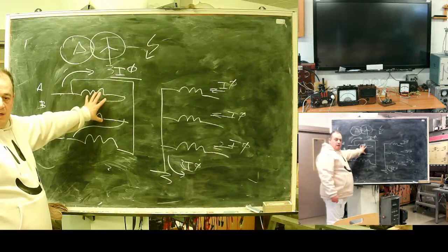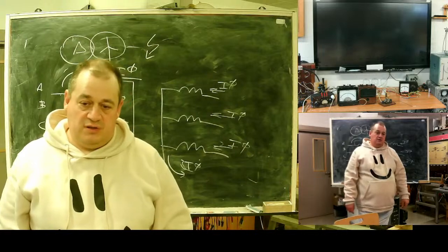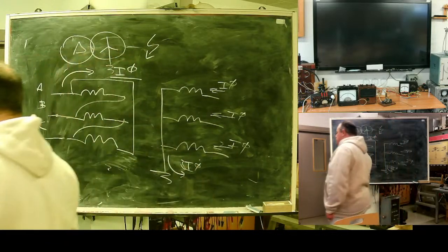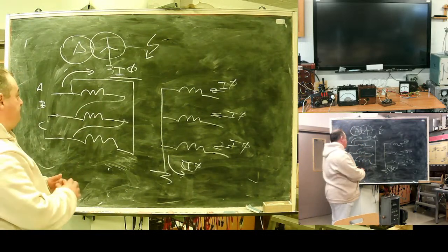Delta is a short circuit. A shortened circuit for zero sequence. Zero sequence current will circulate in the delta connection.